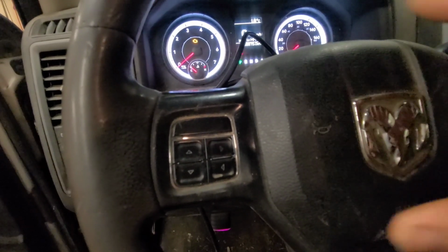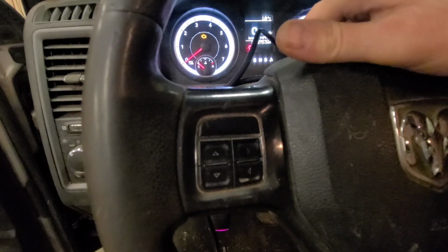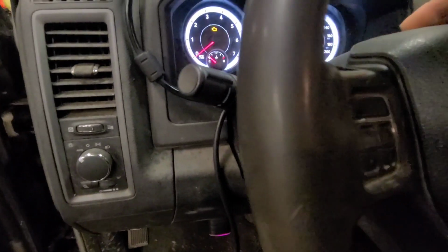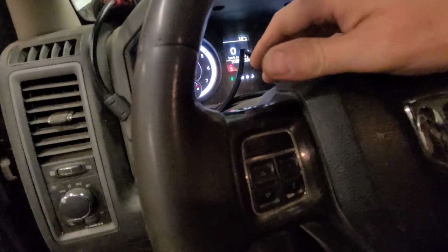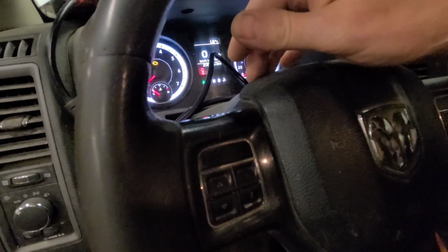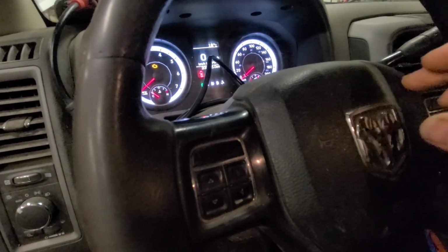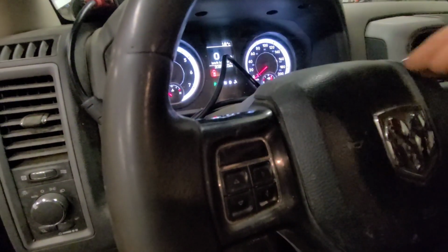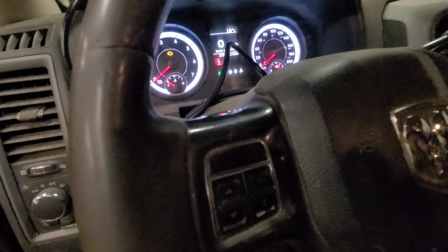We have to pull this airbag and steering wheel off and the steering column covers off. So first the covers come off and then the release for the 3 ears on this airbag. There's 1, 2, 3, but you have to turn the wheel and you have to go from behind. So let's get this apart.